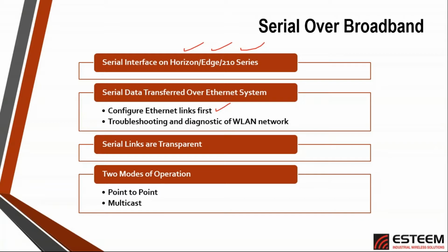If all the sites need to hear all of the data, then all of them can be done in a multicast format. The beautiful part of that is the Ethernet back end, or the Ethernet communication link that's established prior to this. It actually handles the multicast traffic so that you do not need to identify which sites in the network are repeaters, anything like this. All devices within the network will receive it if put out into a multicast packet.